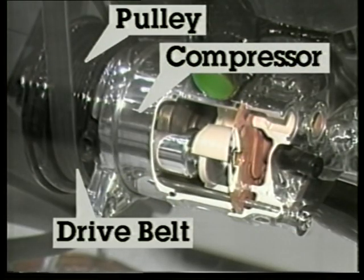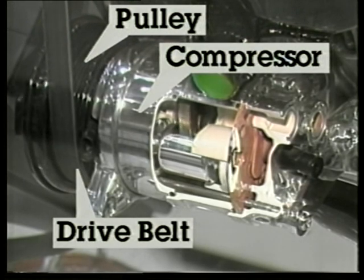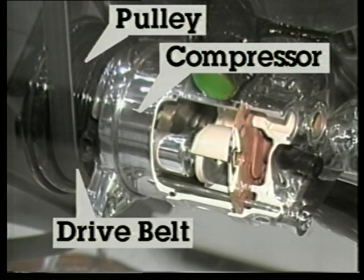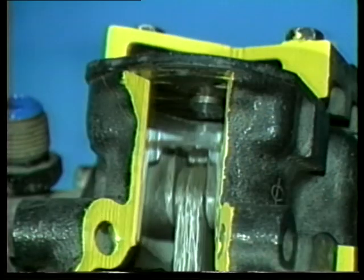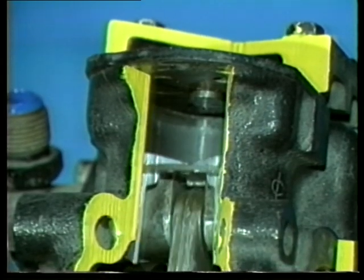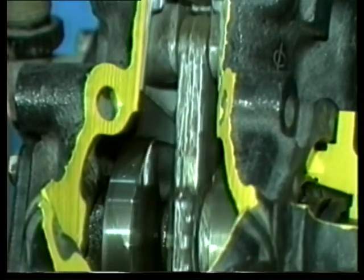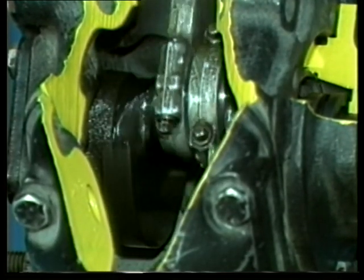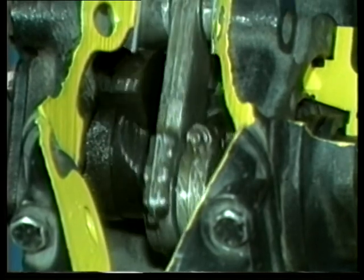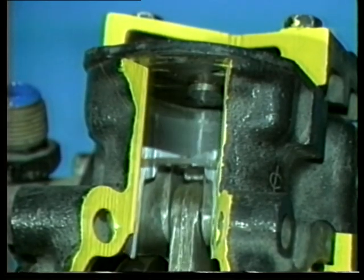The compressor is normally driven by a V or ribbed belt running off the engine crankshaft pulley. Engine power is transferred to the compressor by the drive belt. This cutaway shows the basic action of an older V-twin type compressor. The pistons slide up and down in cylinders to produce a pumping action. The crankshaft is driven by the compressor pulley and forces the rods and pistons to move.